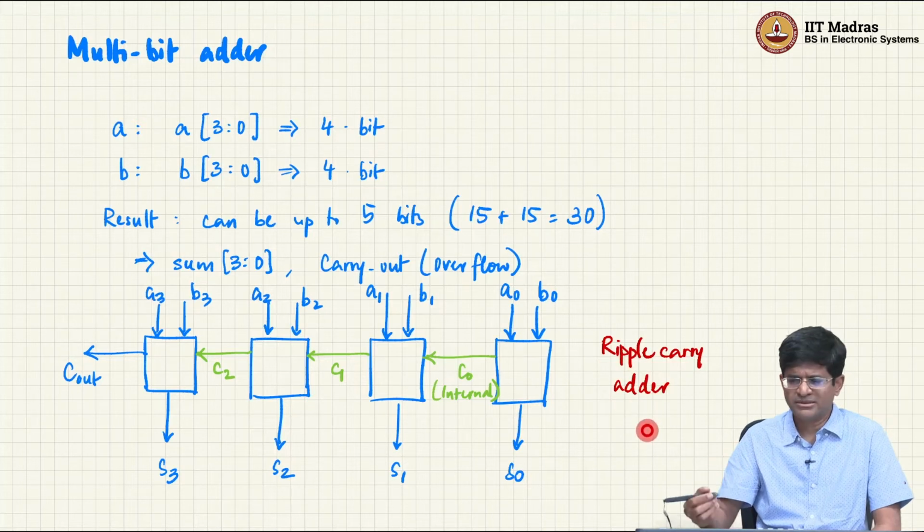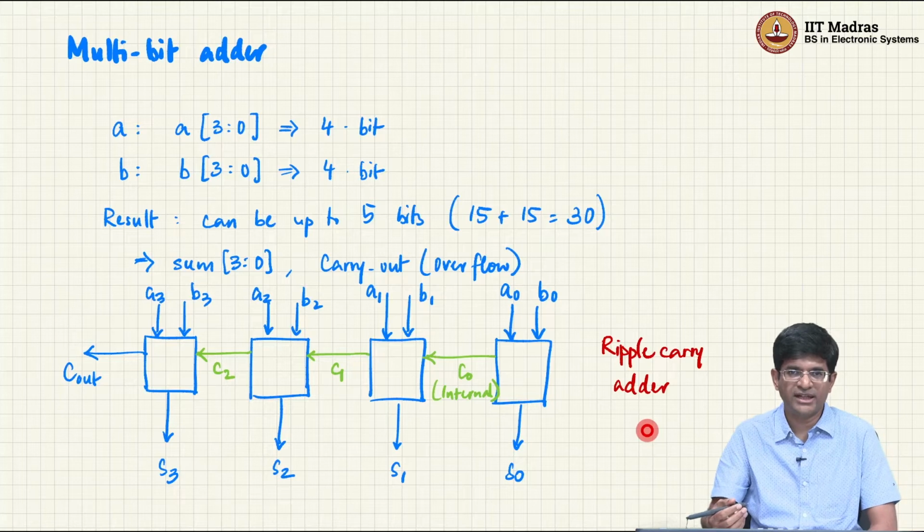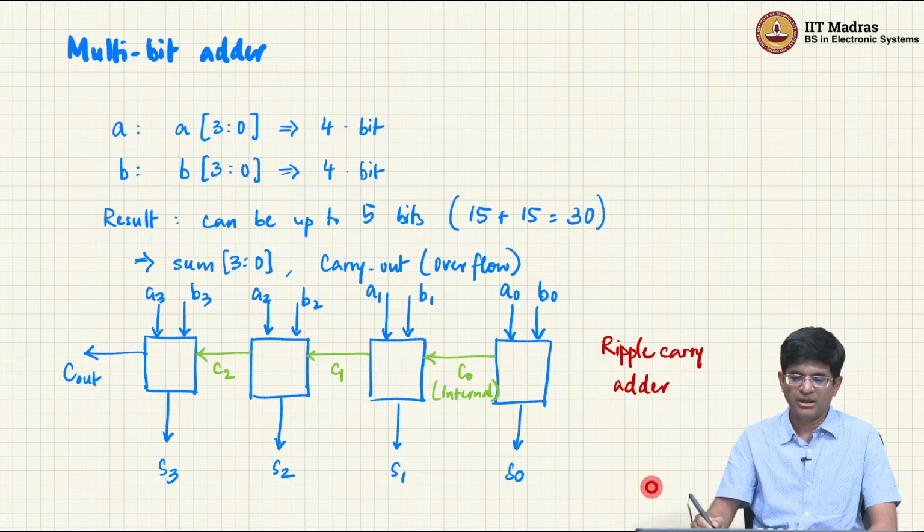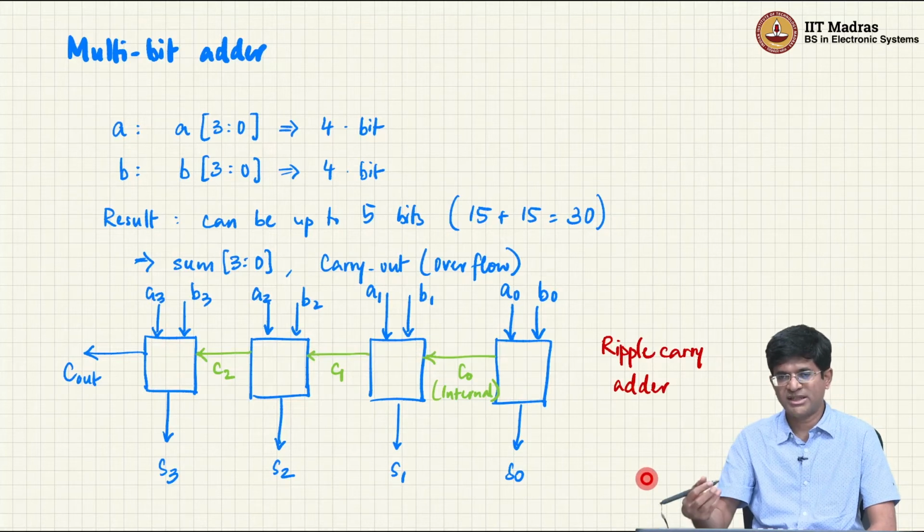You'll probably see there's a lot of study about different kinds of adder architectures. The ripple carry is not normally considered a very efficient form of adder because it has this problem with a long carry chain. But it turns out that in FPGAs, which we'll talk about later, ripple carry chains are actually extremely optimized and quite powerful. So ripple carry adders are good enough for a lot of purposes, and this is how you can build them.